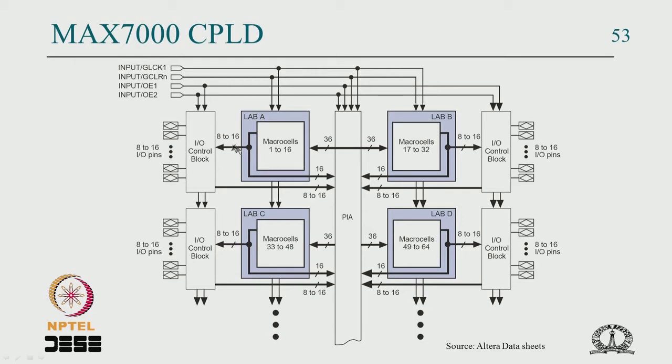So now you look at this, you have a macro cell section, the input of it. Here we have 36 inputs coming from a huge switch. You can think of it as a crossbar. We will see what a crossbar is, but this switch output is connected to the input of the AND gates. So that is programmable. You have 36 inputs and their complements available as vertical lines as in the picture. And you have an AND gate, and a few AND gates go to an OR gate, XOR gate, flip flop and so on.